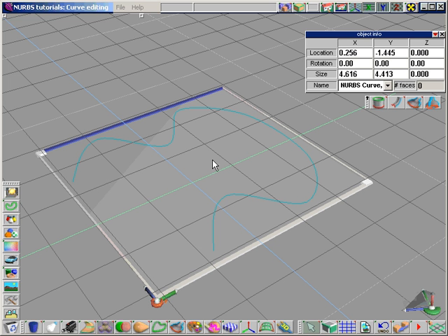This tutorial introduces the NURBS curve editing tools. Each curve will appear within its own draw panel, accompanied by a NURBS surface toolbar, which will be covered in a later tutorial. If you right-click the blue spline, its control points will be highlighted yellow. One will be green, indicating that it's selected.